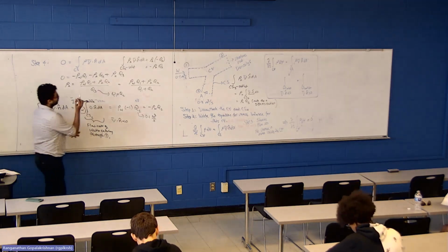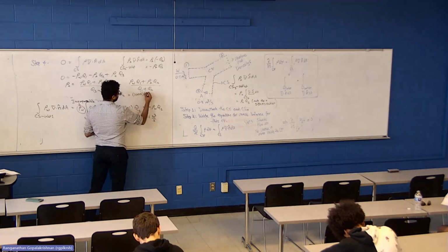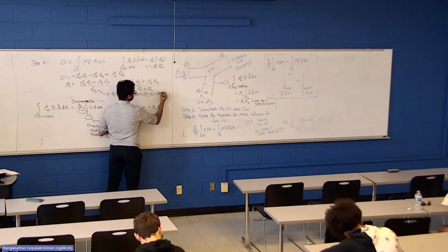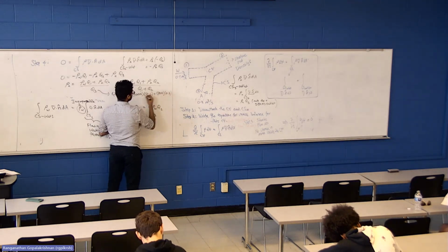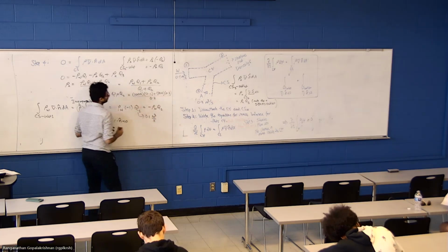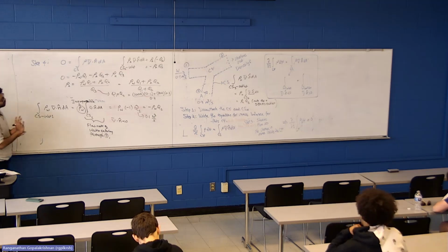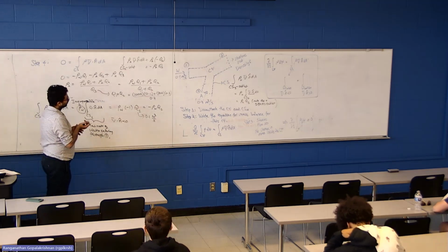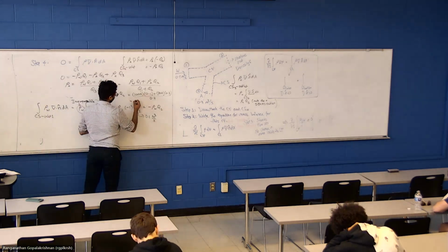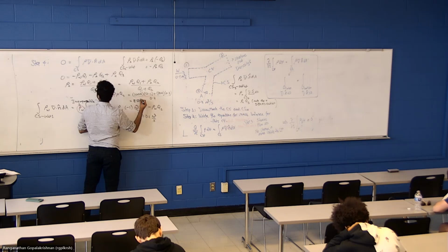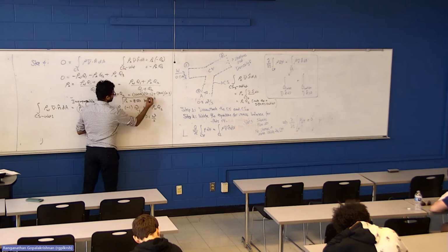And do the calculation if you want. So this would be 1000 times 0.3 plus 800 times 0.1, plus 800 times 0.3 divided by 0.4. Which is 250 plus 600, 850. 850 kg per meter cubed. That is the density at the exit stream.